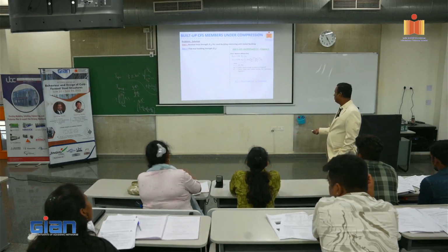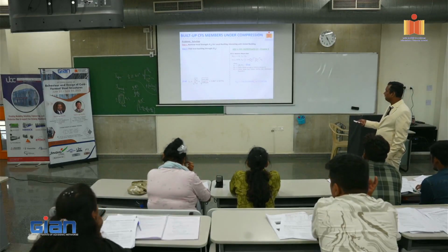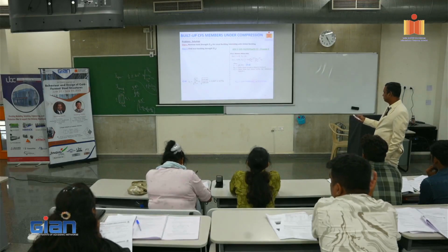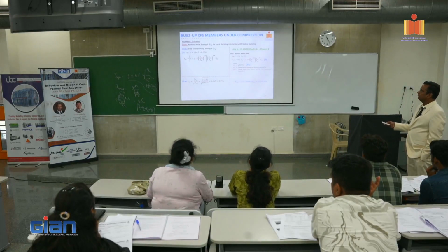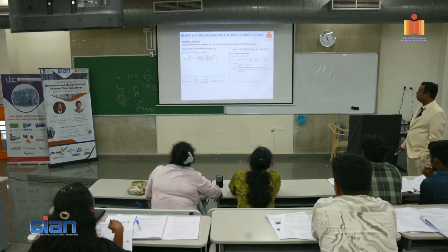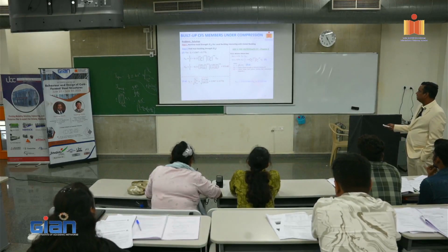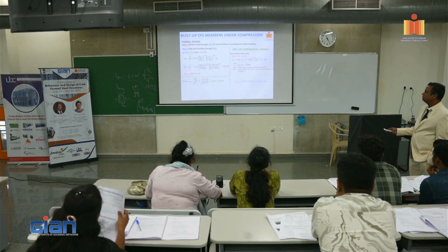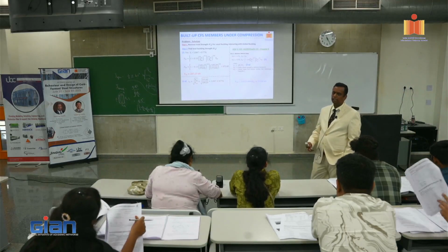So now, here P critical is 109, Pne is 372, so when we do so we get 1.847, which is greater than 0.776, so I have to use this equation. Pnl equal to 1 minus 0.15 times (PCRL by Pne) to the power 0.4, and so on. I know that PCRL equal to 109.29, which I already calculated, and then Pne is 372. We do all this and we get 207.25 kilonewton, it is Pnl. Right? Is this the end of the story?